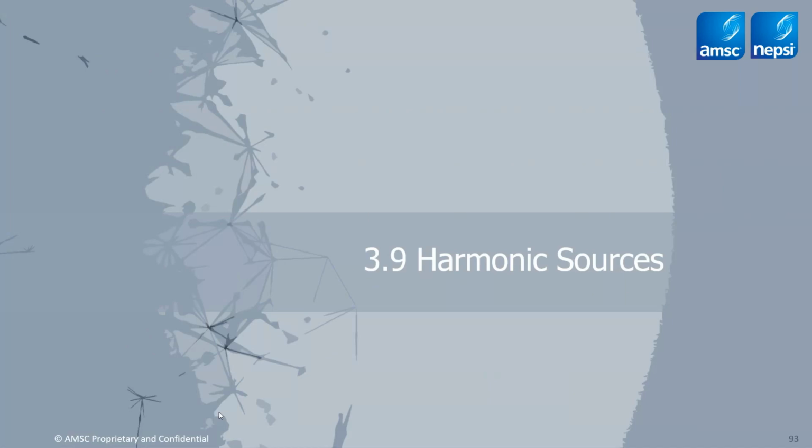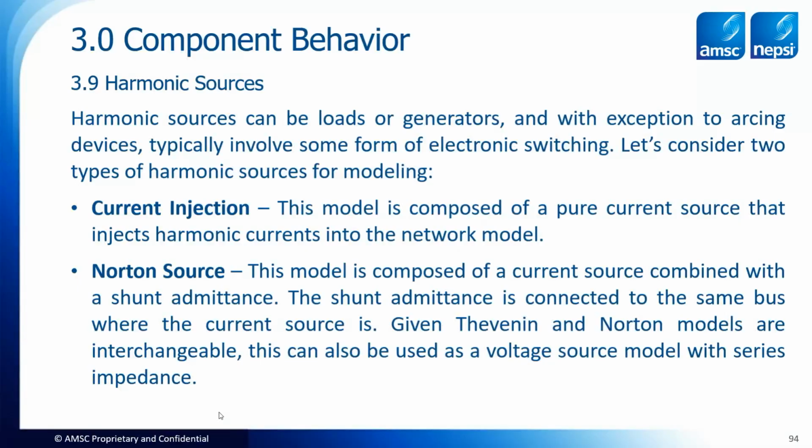Okay, the last part of this is harmonic sources. And this is where a lot of times you may end up having a challenge getting your data, similar to the grid. When you get in the grid model, you're going to run into a natural challenge unless you're the utility and you happen to be able to produce those numbers for your connected customers. Harmonic sources, from my perspective, should in every case be supplied by the manufacturer. That's my recommendation.